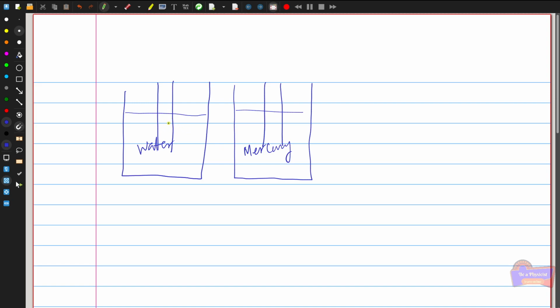the surface tension. In water, suppose you dip the glass plate or a glass tube, you can see the water is clinging to the glass tube upwards. That is, the water molecules cling to the surface of the glass and rise along the plate, as shown in this figure. If you plot the tangent line to this cling surface, you can see there is some angle. This angle is known as the angle of contact, which can be measured as theta.